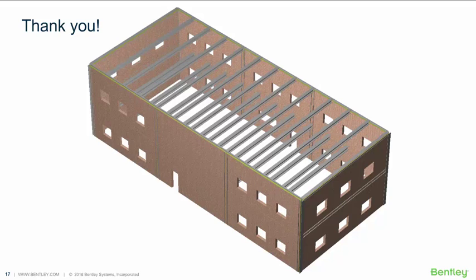So that's done automatically for you. You might have other situations where, instead of the entire intermediate level, as I'm calling it here, being open, there's just maybe a little mezzanine area. That's another situation where you have some mass that you can either associate with that mezzanine at that level, or you can take it to the roof level above.